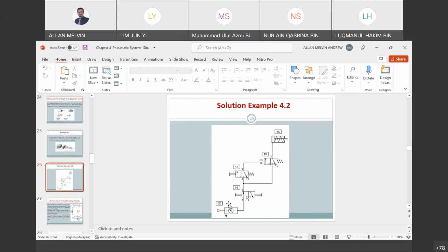Okay, 0Z is your compressor and your FRL unit, and 0S is an emergency button. Emergency button to stop the whole circuit if anything goes wrong. Or on your laptop, what do we call it? Hard reset, or hard stop. Meaning you are forcing a stop, forcing something out of nowhere. So in a simple way, this is to stop the whole operation: emergency stop. So 0Z is the compressor and 0S is the emergency stop.